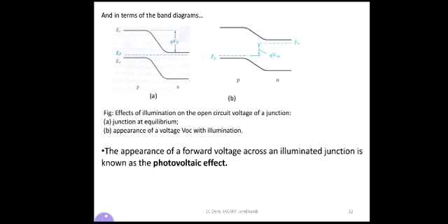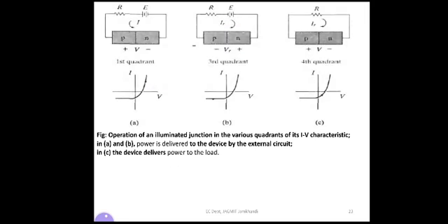In our semiconductor, the minority carrier concentration is increased by optical generation of electron hole pairs. So the lifetime tau n is decreased. This increases the ratio Pn by tau n. So VOC cannot increase indefinitely.